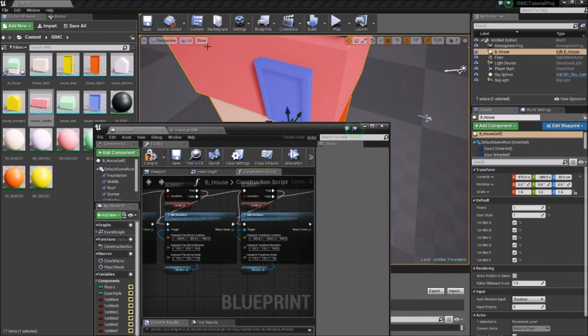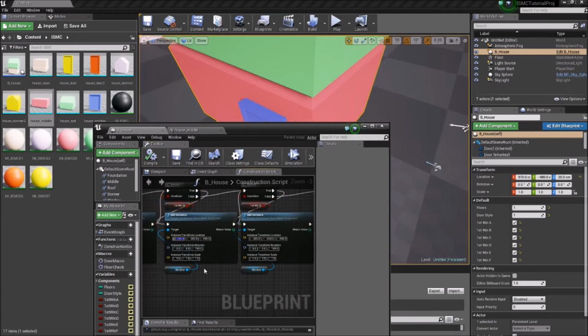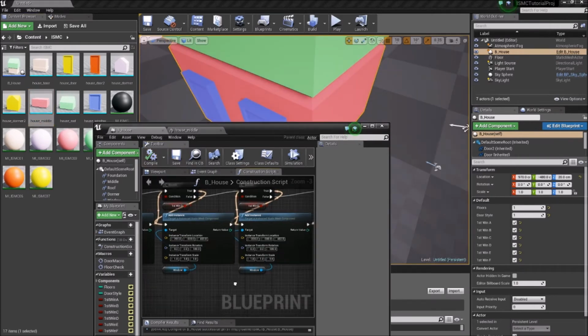This is the fourth window. That'll be right here. So we want to do the same thing, 180-degree rotation in the Z-axis, negative 200 in the X, and negative 300 in the Y. Oh, positive 200 in the X, negative 300 in the Y.